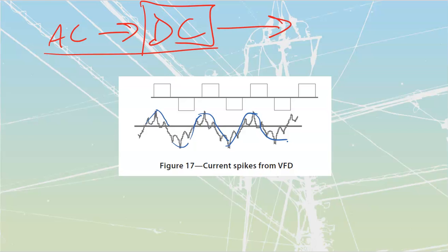Power factor correction capacitors, we generally get more transients that are going to happen inside of there, and then they're going to react to frequencies, harmonics that are caused by other things. If we do get harmonics that are caused by other components on our system, if they go back into our power factor correction capacitors, we can get some massive problems with overheating and puncturing on those, particularly if we accidentally drive these things into resonance or anything like that.